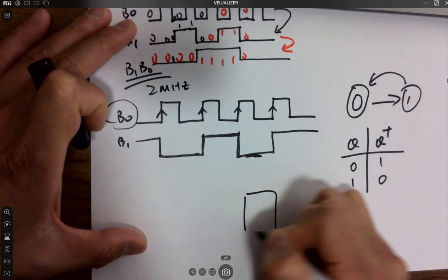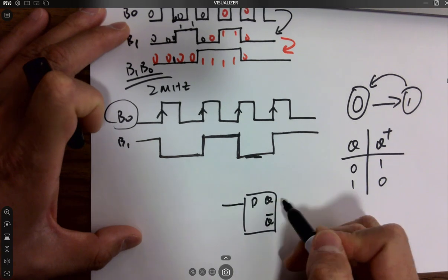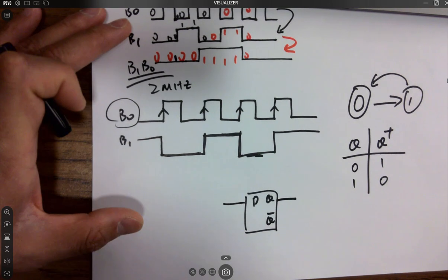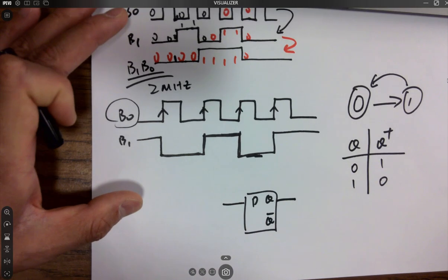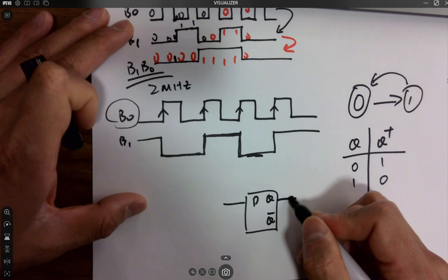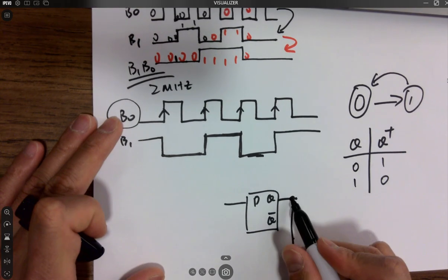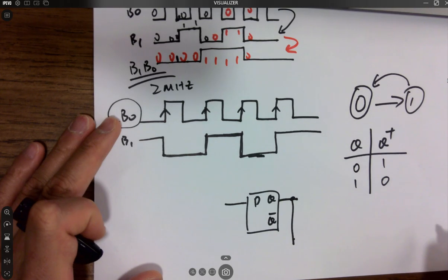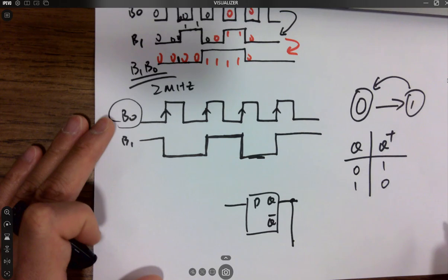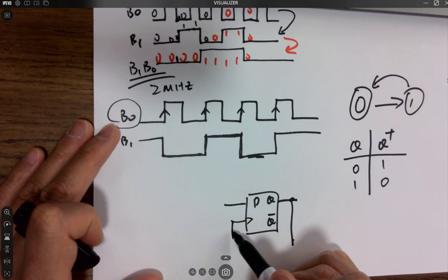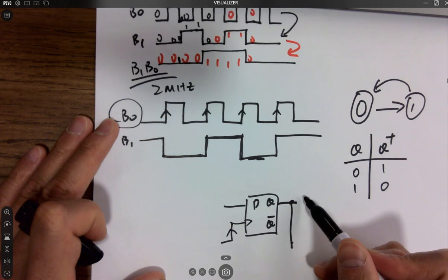If you draw a D flip-flop to hold the state, which is the current state, which is the next state? D is the current, and Q is the next. No. Q is the current. Yeah, Q is the current. Why? Because Q is the output. You can directly see it. You are probing it, right? Whatever you probe over here at Q is going to be the current state. Do you agree with that? Yeah. So what's the next state? D. When the rising edge arrives, D becomes the new Q.